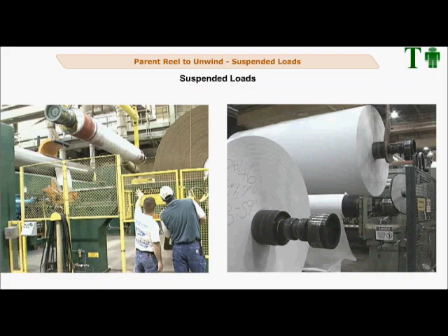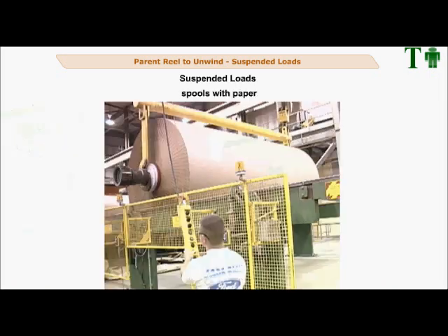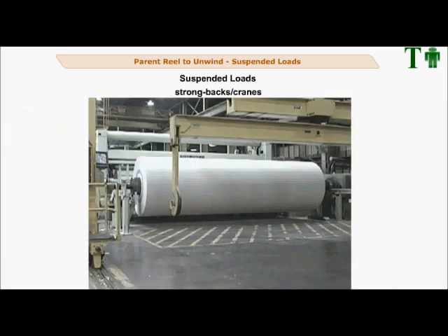Suspended loads. Be aware of suspended loads and never be under them. Examples of suspended loads are empty spools, spools with paper on them, strongbacks with nothing on them, and even items being carried with the crane for maintenance.